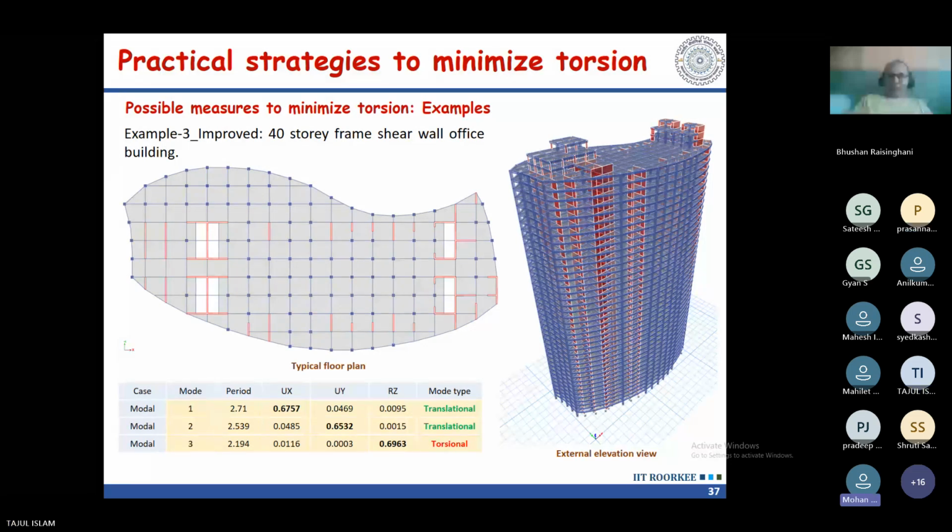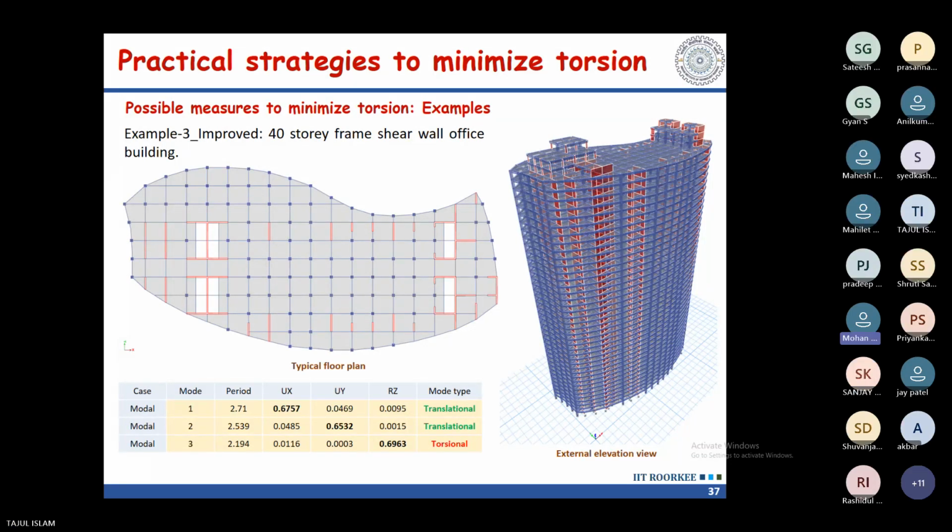So for an office building, it is okay. And if you have a residential building with a large basement area, with individual towers, around 15 to 20 towers, each tower is only 10 meters by 3 meters, and those are all connected by a single corridor. In that case, how will these torsional irregularities be checked for each and every tower? So there are individual towers, and at a certain level corridors are provided to connect those towers.